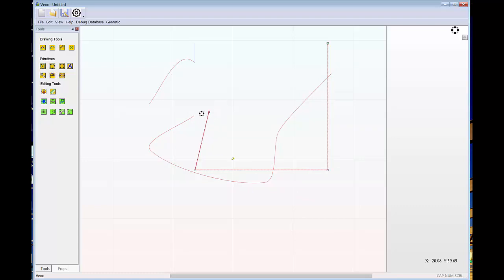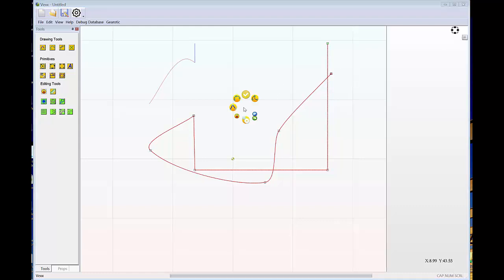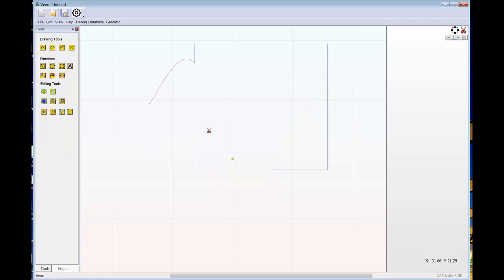If I go to the node editing and I pick up a node and just bring it close to that node, however, I've just created a new contour which comprises all of them again. So keep note of which control key modifiers are lit up in the corner, and you'll find that you should be able to trim things fairly nicely to make them do whatever you want.